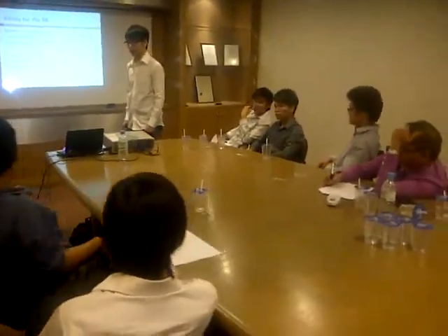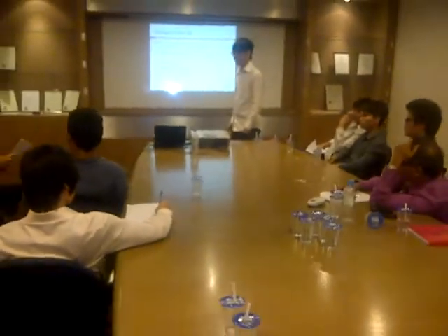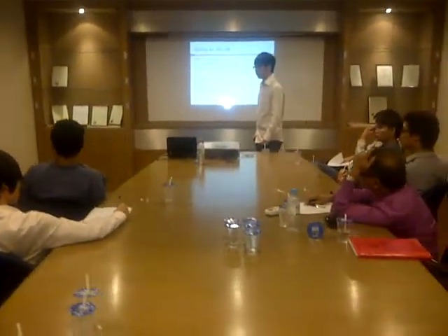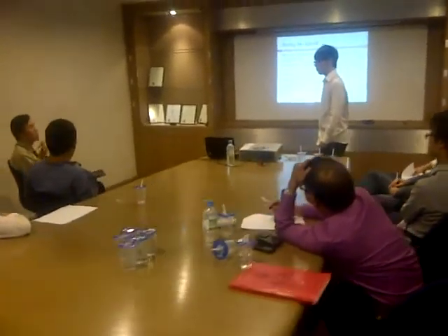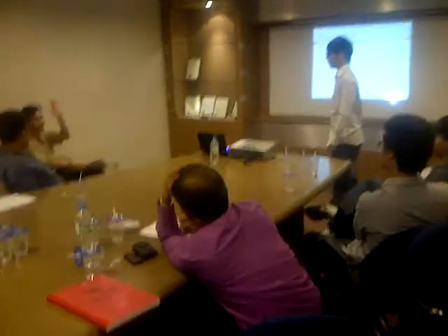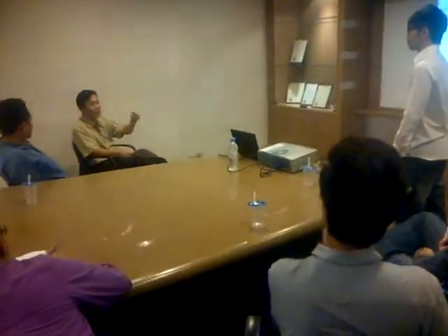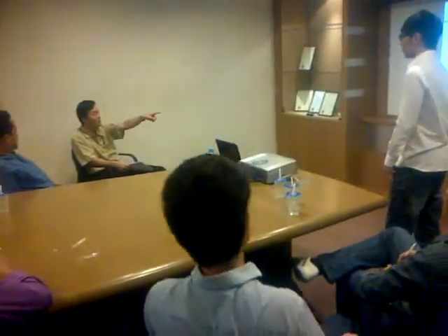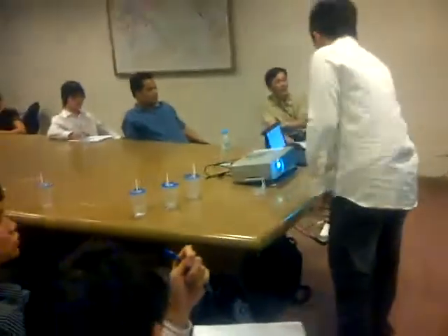You go there and survey how many people are using the socket outlet with how many computers during a very peak time. Once you get that, I even allow some safety factor, which means we can multiply by 1.3. An additional 30% on top of your peak is very safe already. Even so, when you calculate back, it is still far lower than this. I'm very sure. Okay, continue.